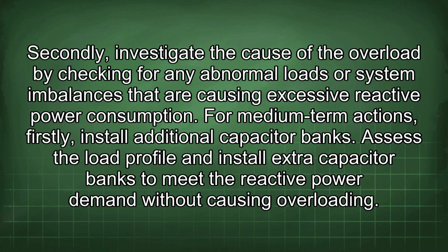Secondly, investigate the cause of the overload by checking for any abnormal loads or system imbalances that are causing excessive reactive power consumption. For medium-term actions, firstly, install additional capacitor banks. Assess the load profile and install extra capacitor banks to meet the reactive power demand without causing overloading.